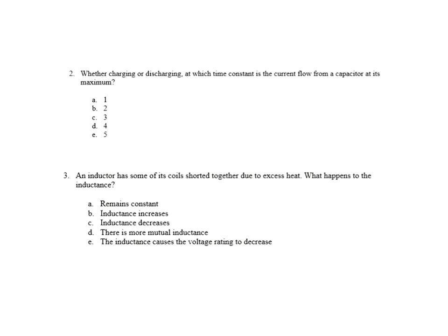All right. An inductor has some of its coils shorted together due to excess heat. What happens to the inductance? Well, when you short coils together, you effectively reduce the number of coils. What happens to the inductance if I reduce the number of coils? Well, the inductance decreases. The answer would be C for this one.